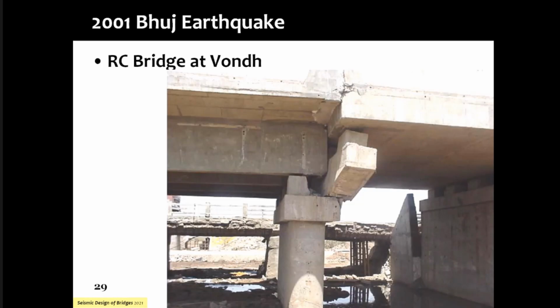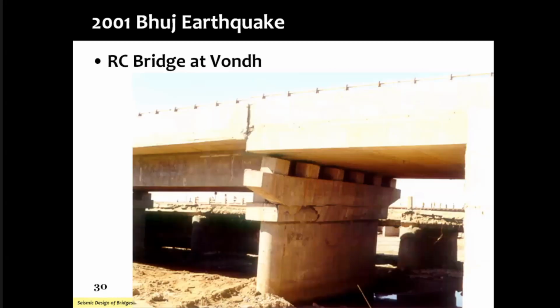I would urge designers to adjust the small change in the main spans themselves and make 4 or 5 spans have a little extra meter length, and make sure that you don't provide such shorter spans. Every time there was a longer span, or one short span or two short spans, there was trouble at the interface between the two. I don't want to show a large number of earthquake damage pictures here today, but I want to push the concept in so that you'll understand that this is not an acceptable strategy.